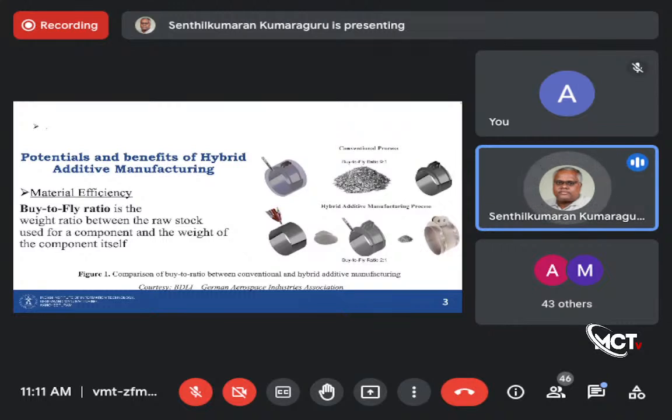So you are using a tool to successively machine the final shape, and you are wasting kilograms of material per kilogram of part. You bought titanium material, Ti-6Al-4V, which is extremely expensive. And this is the stock that you produce through AM and finally finish machine. So you waste only a very small amount of material compared to this as waste. That is what hybrid additive manufacturing is. You take a part and slightly enlarge it by giving a machining allowance, make it in AM, and then remove that delta volume that you added as machining allowance, and you waste a little amount of very expensive material.